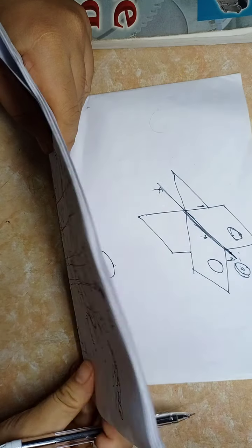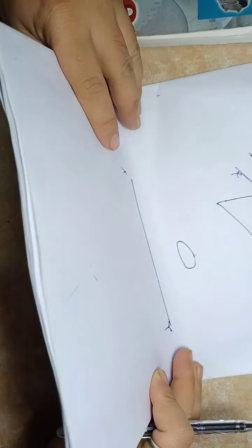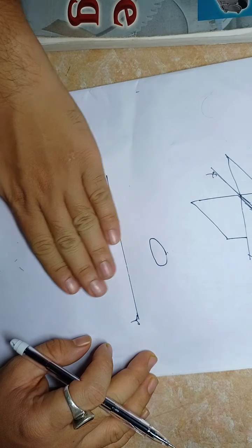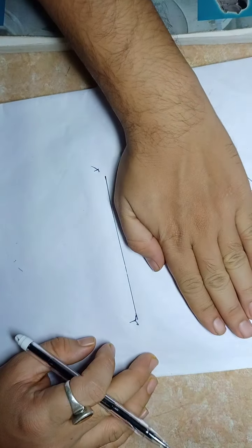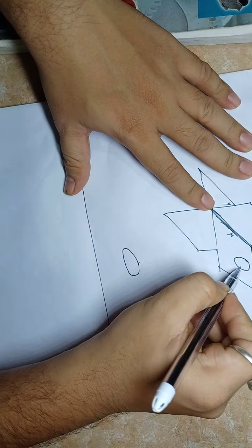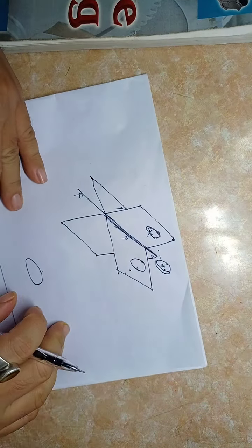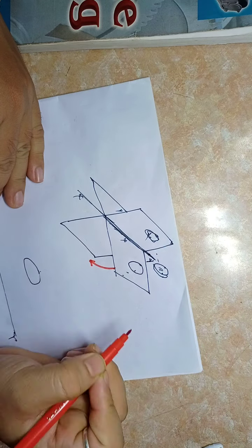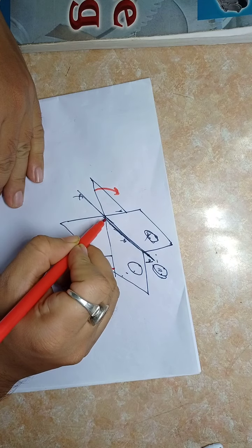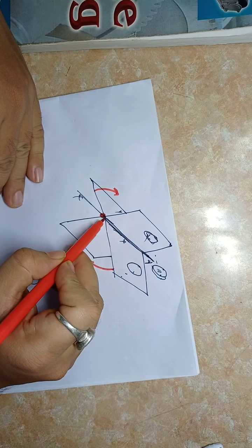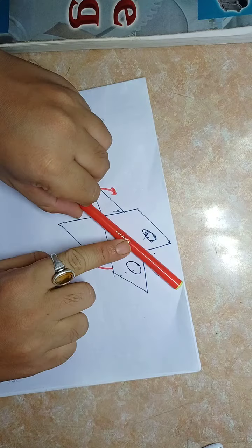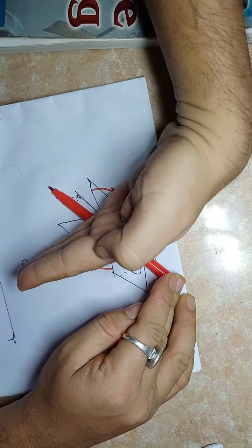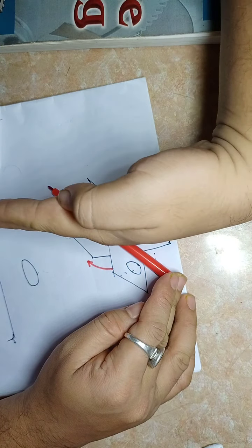No, because your paper is exactly parallel here, this side is also parallel to the above side. That means to draw these two together, what you have to do is rotate this plane. Rotate the whole plane. Consider this as a pivot or a pin joint here, and rotate this plane completely to merge it along with the vertical plane.